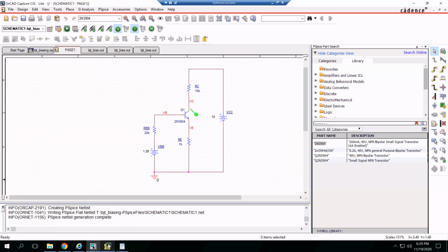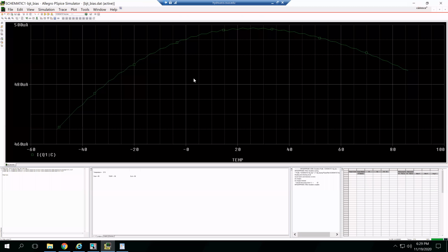You have to come down here and click on the blinking icon to see the plot. But now you can see that the change is a function of temperature, right? So usually 27 is the nominal temperature. So that's kind of interesting, right? Because it's right at the top of this peak here. And depending on what direction you go from nominal, it's dropping off for this particular component, right?